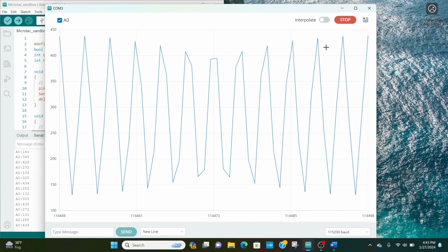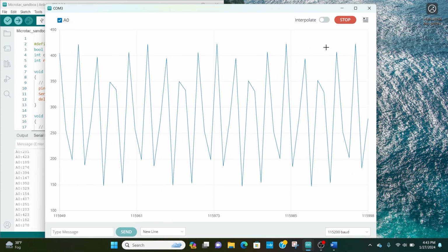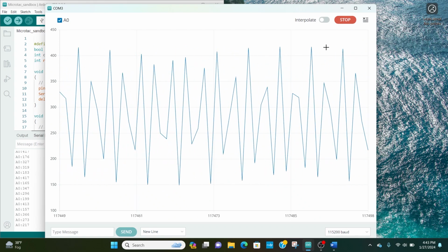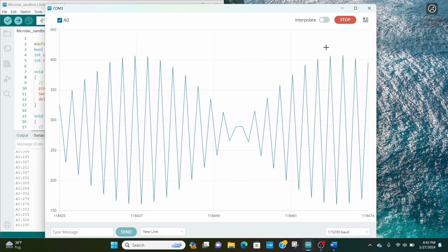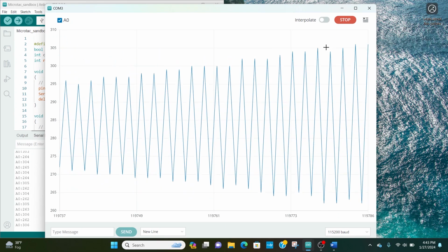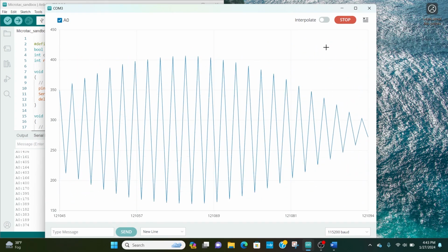And we start to see some distortion there. As I go even higher, it almost looks like the signal's modulated because we're just not getting enough data points per period. And if I get right up close to the Nyquist criteria, oh my gosh, look what's happening. I'm getting a really funky, almost modulation, like I say, on that signal.